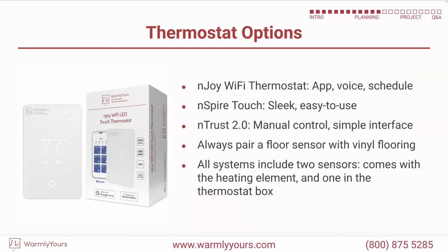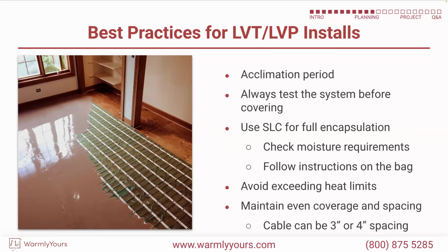There's a couple other things we should probably point out on that slide, Scott, maybe the tools that are needed. Yes, good call. When you're doing a self-leveling install over this, you're not using normal self-leveling tools. You're not using a gauge rake to get your thickness correct, because gauge rakes have little pins that stick down, and as soon as you do this and pull across it, you're pulling the whole system up. Oh, that would be terrible.